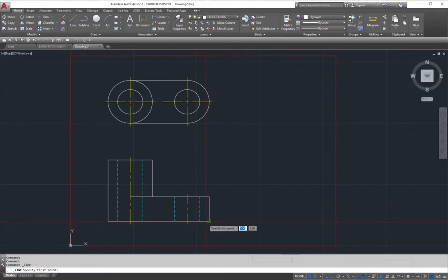But look what happens. If I just go and place my cursor right here, it gives me that end point or intersecting point reference. And then if I just place it there, I'm not going to click, but if I just go and slowly move it, see how it gives me that broken line right there? That tells me that is my F11. That is my object snap tracking. It temporarily allows me to move from one point to another without necessarily clicking anything.